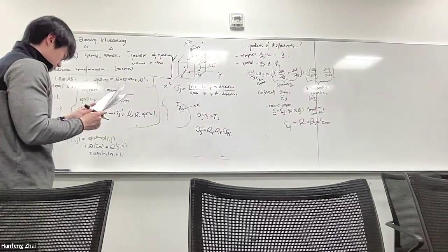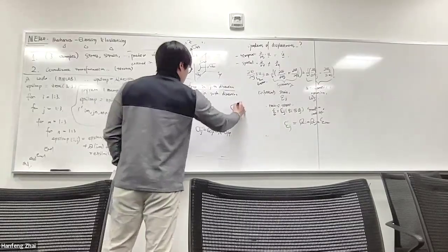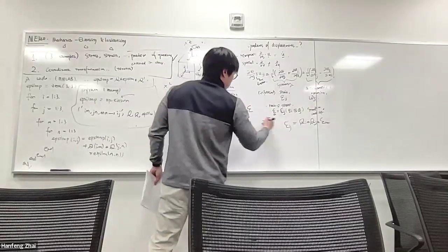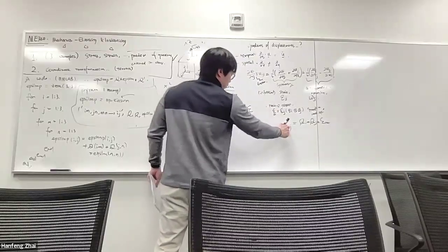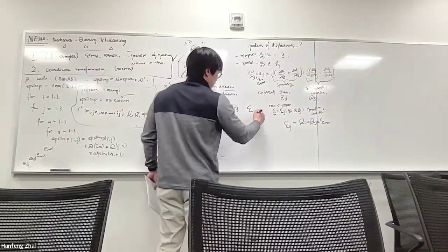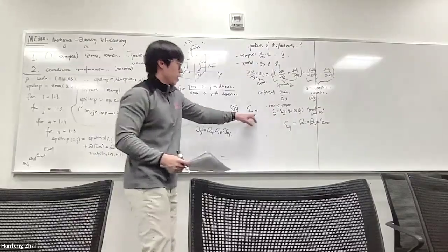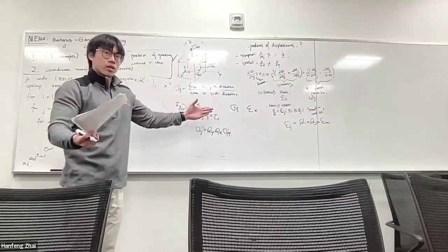And great. So now we learned what a stress tensor is. We also learned what a strain tensor is. Let's say now we don't want to write ij. Say they're in different coordinates. So we have epsilon kl, a second order tensor, and stress sigma ij, also a second order tensor.